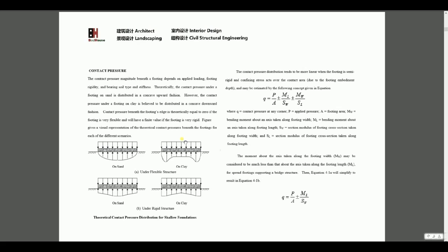So it is very important to think of the soil bearing capacity. For wood construction or a house, like in Richmond, if we don't have a basement, the bearing capacity is usually 1,000 psf, meaning 1,000 pounds per square foot.